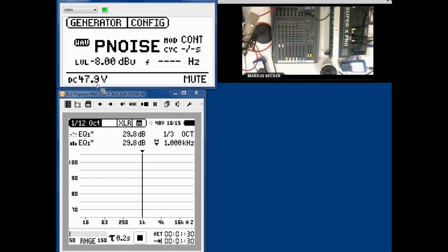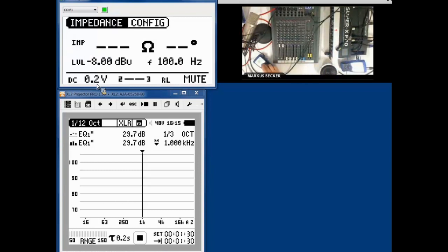Well, here we have to take a look at the cable connection. And for that purpose, I'm going to disconnect the cable here from the mixing console and plug it to my EMA Pro, because I want to find out whether this cable is working fine or not. Well, let us assume that the other end of the cable is far away, not like on this place here. So I want to show you how you still can test the cable. First of all, you activate the cable test, and then you use this remote cable test plug, which I connect to the other end of the cable.